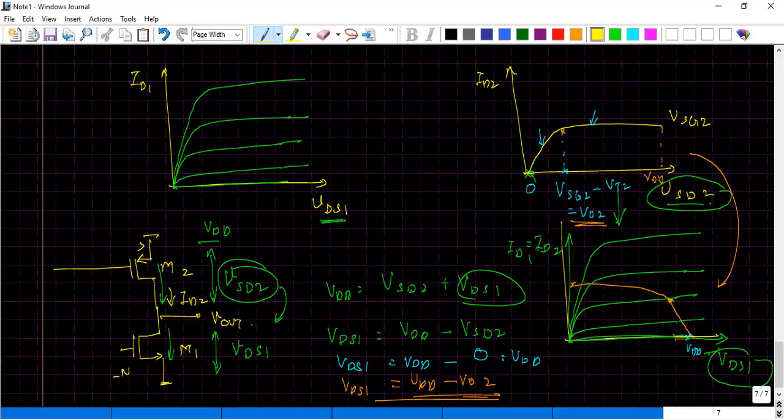So now what happens is I have to look for regions where both my M1 and M2 transistors are in saturation. So again, we are able to see that there is an intersection between those two graphs at these locations, which I can mark through these yellow dots or yellow cross marks. Now clearly it indicates that it is only after this particular region my M1 transistor gets into saturation, and clearly for my M2 it is after this particular point where my M2 enters into the saturation region.